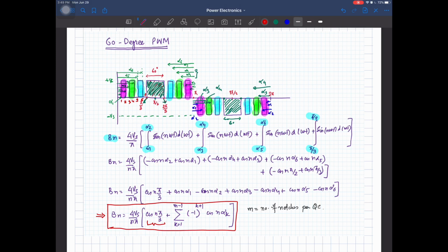So this is one of the PWM techniques and it is very efficient when you are using microcontrollers, simple low computational power microcontrollers, because you can pre-calculate all of these angles and you can program your microcontroller timers to generate gate pulses for your switches at the specific time, right. Instead of having runtime calculation, you will be using the predefined calculated angles and you will be generating gate pulses for your inverter circuit. So for implementation with a low computational power microcontroller and processor, this is the best PWM technique.